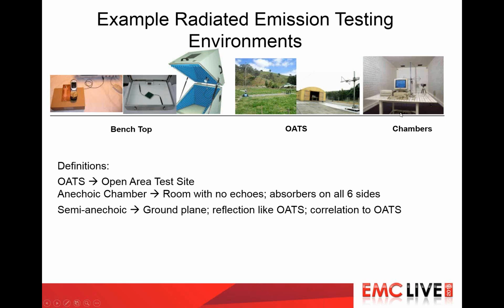And a lot of companies are starting to build small RFI chambers. I've actually been to a company that built a chamber that was made out of fencing. So you're trying to build a Faraday cage around your device to eliminate the background noise and RF signals, to just concentrate on the RF energy coming out of your device while you're testing.